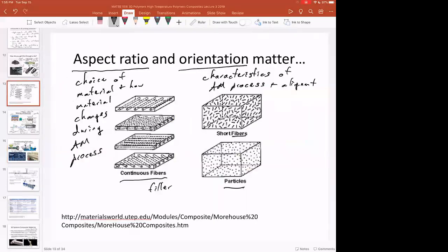We mostly want composites that have good dispersion of filler in matrix. And so that means good wetting, that means good sizing. In order to get something to mix well, you need to have good interfacial compatibilization between the two phases. If they don't mix, you're going to wind up with clumps of stuff, and that just doesn't make a very good material. And so composites are not only designed for dispersion in the end product, but in order to get these things processed correctly, you also need to have good dispersion.